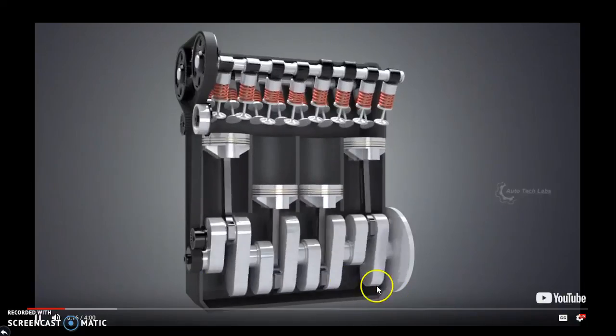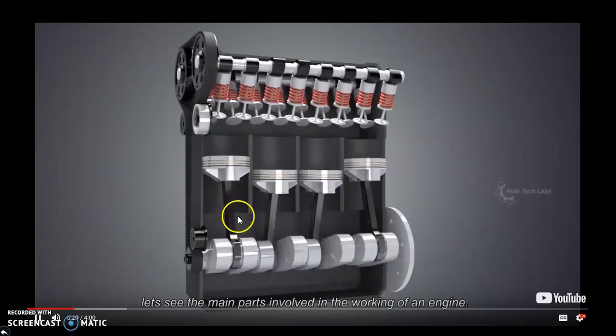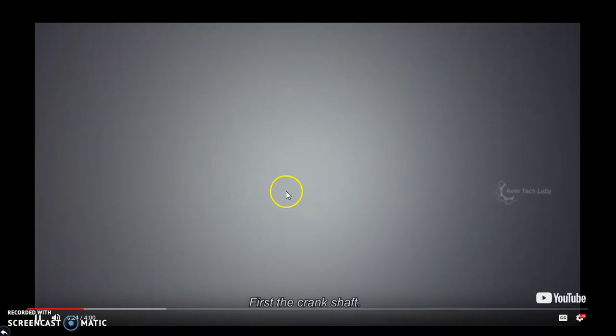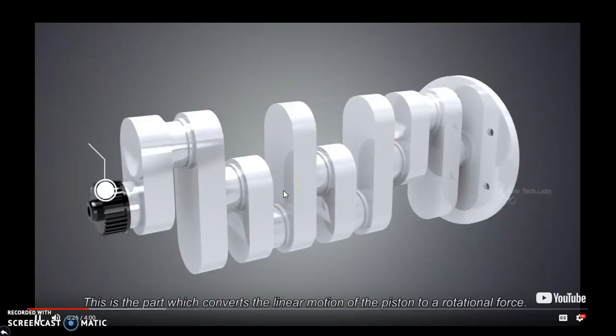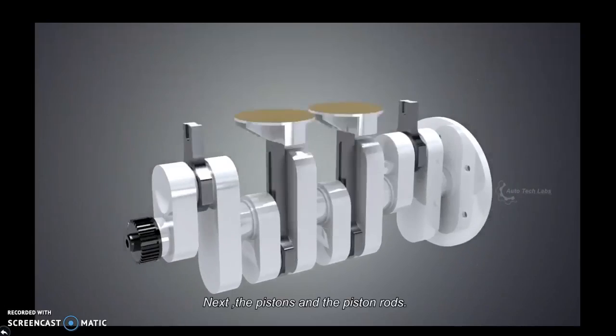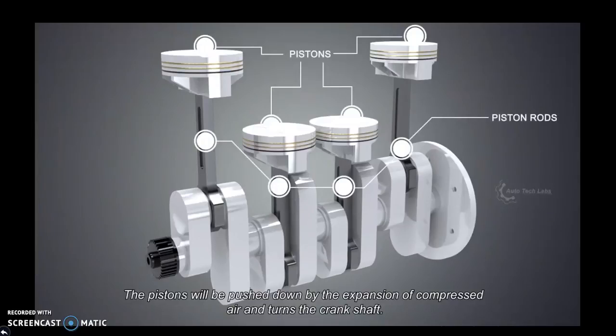Here you can see the rotation of the crankshaft, which is causing the pistons to move up and down along the cylinders. As you could see, the pistons, not all four of them, move together. This is the basic concept when we study the firing order. The different firing order is responsible for the stability and efficient power transmission of the system.